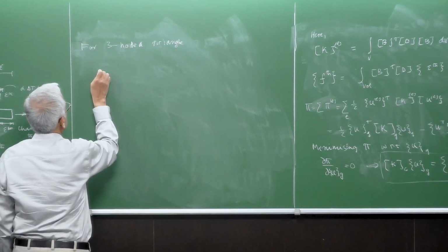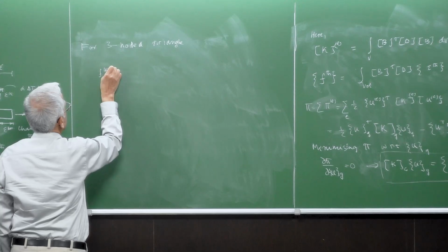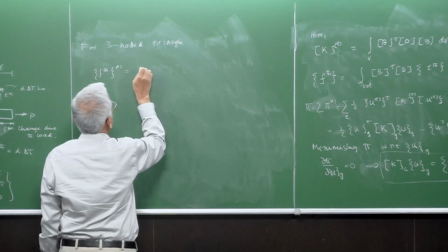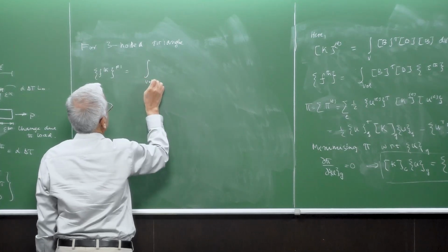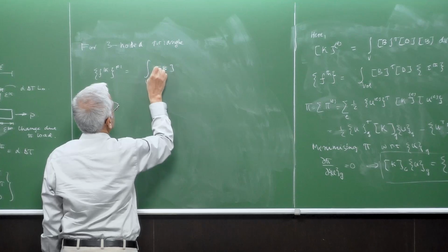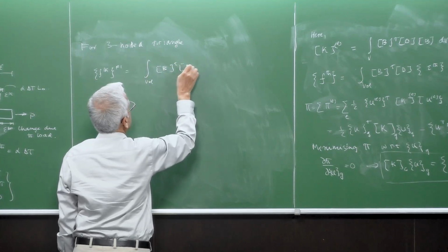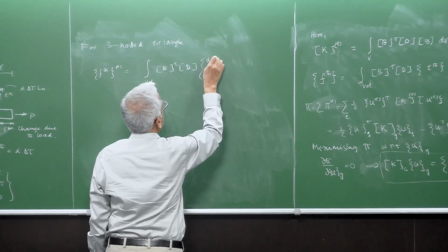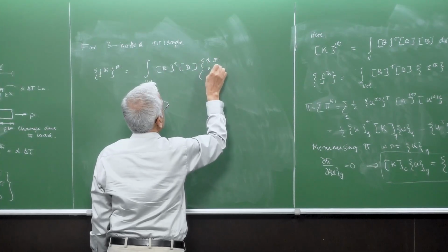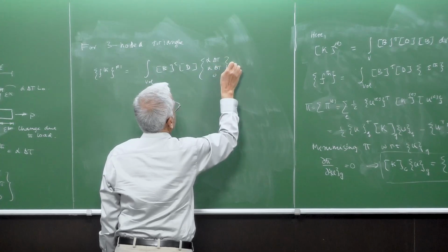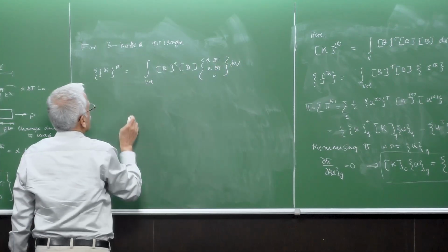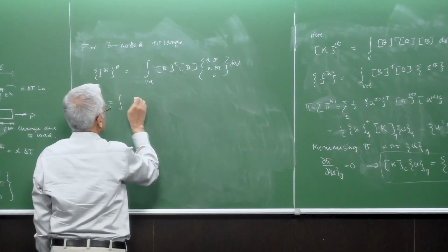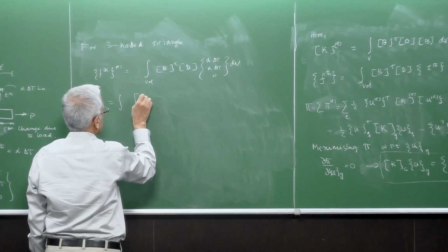So what we have here, F thermal for the element, is nothing but B transpose D, and this is epsilon thermal, which is nothing but alpha delta T. So continuing this one, this B transpose is nothing but this.